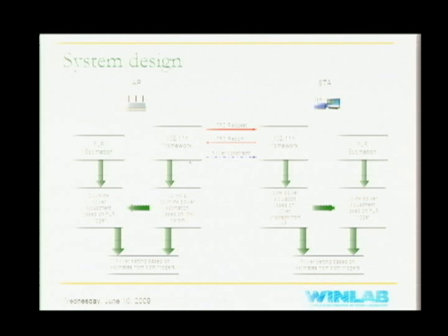We always adjust starting from the power decided based on RSSI measurements. You either increase it or decrease it. And the same is the case on the station side. And finally, with both the power estimates in hand, you need to decide how you are going to affect it to the wireless card.